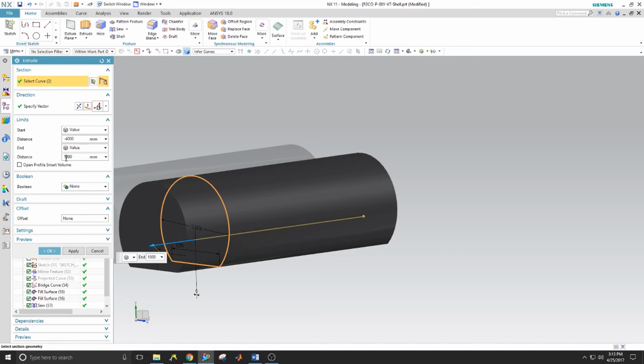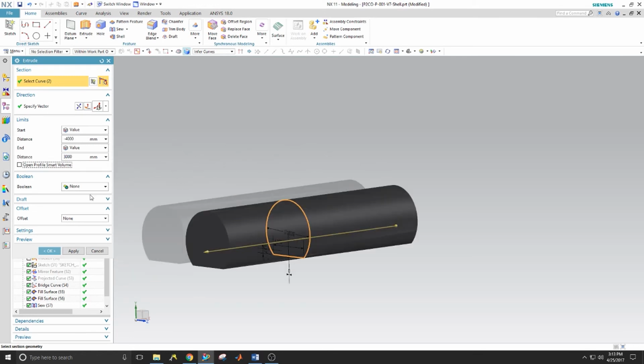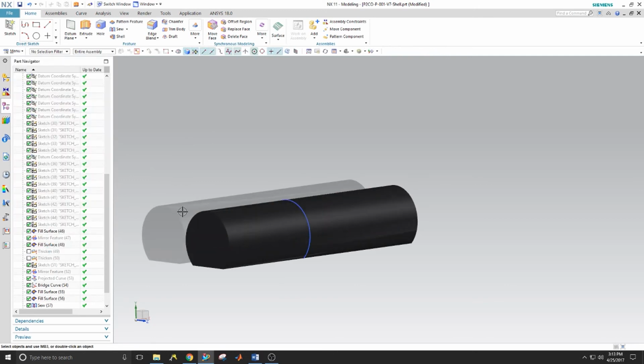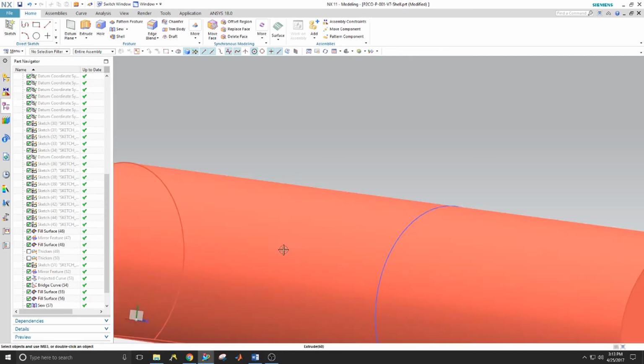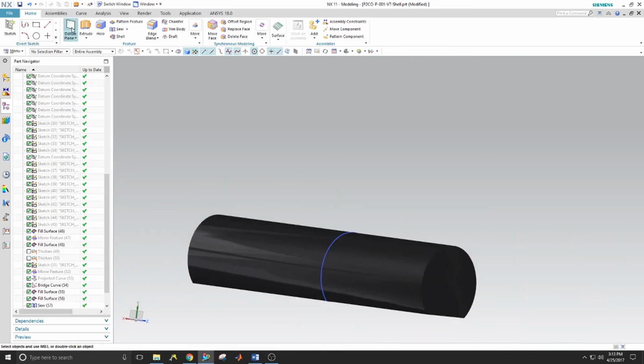Next, we're not going to be combining our pod in this stage. We're going to be doing that later. I'm going to make the back a little bit bigger actually, because we need to allow the air some space to equilibrate after it leaves our pod. And hit OK. As you can see here, we now have a solid tube in which we'll be running down, and this will be our air domain.